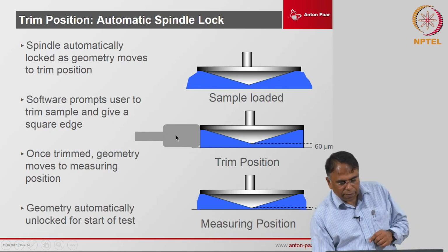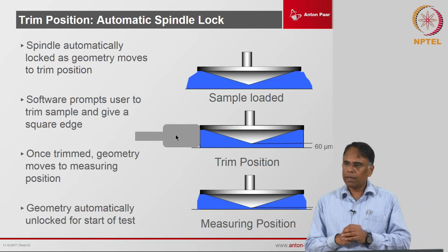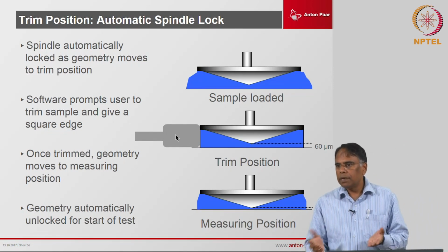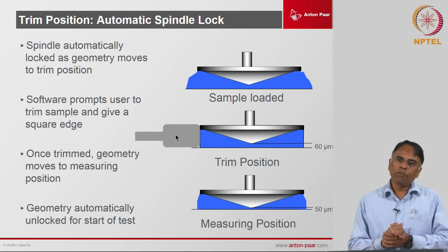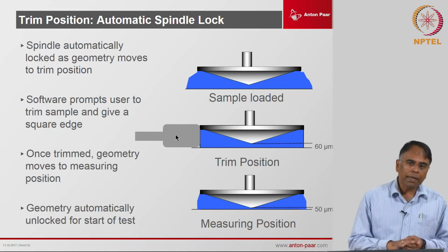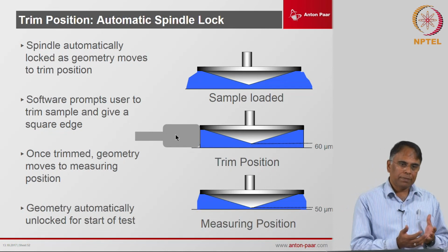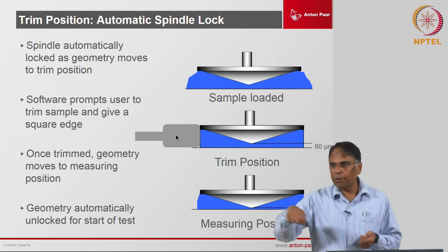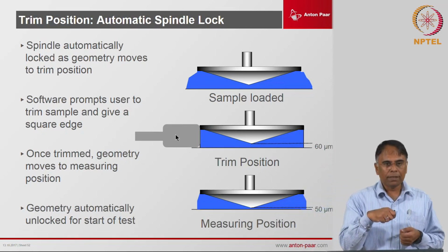Trimming the sample is important. If you take viscoelastic solids, for example asphalt, trimming is one of the most important parameters, and if you are going to trim samples which are hot, make sure that the trimming tool you are using is also warm enough. Do not take a cold tool and try to trim that. You are giving a very big thermal shock to the sample.